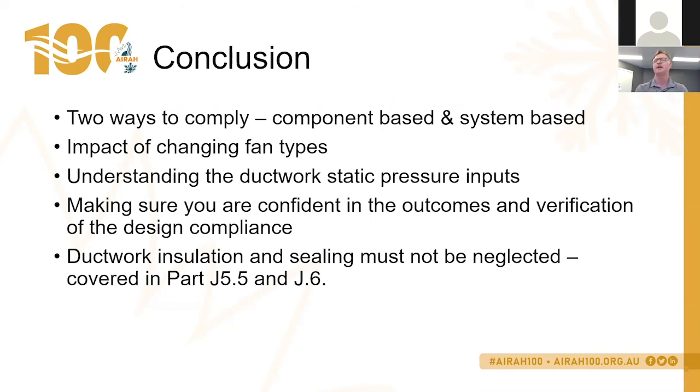The reason the calculator showed that different types of fans have different efficiency allowances is for when you're comparing an axial to an axial and a centrifugal to a centrifugal. Under the code compliance, you're not really comparing different types of fans to each other and trying to achieve compliance that way.